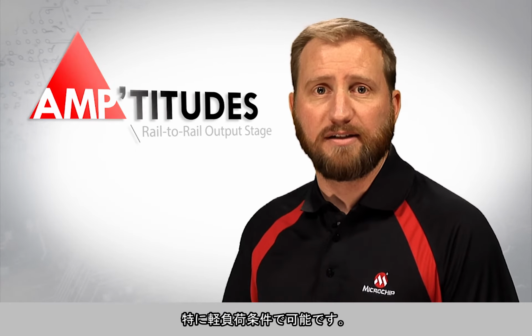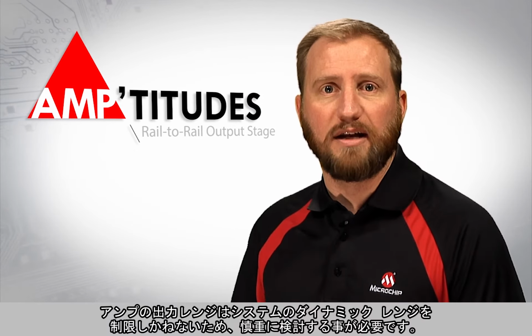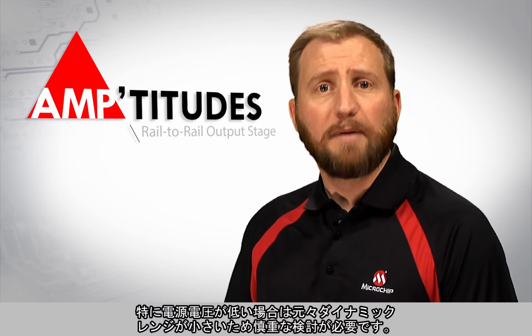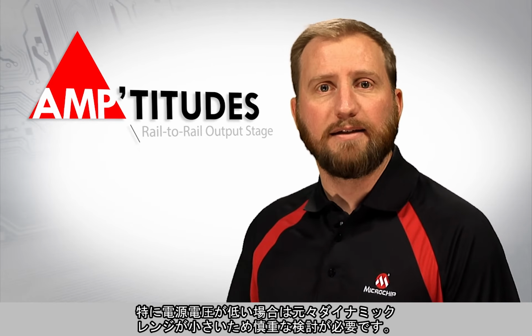Although no amplifier can truly swing rail to rail, many can get very close, especially under light loading conditions. The output swing of an amplifier can become a critical design consideration, as it may limit the dynamic range of the system. This is especially critical with low supply voltages, where the dynamic range is already limited.